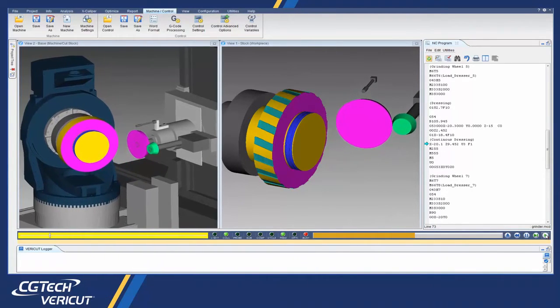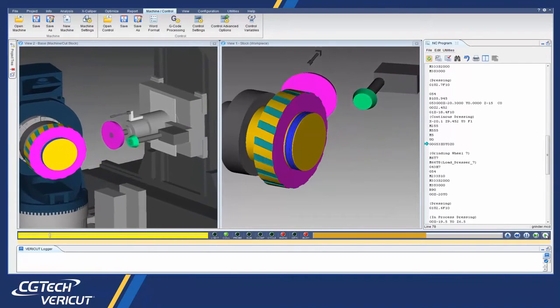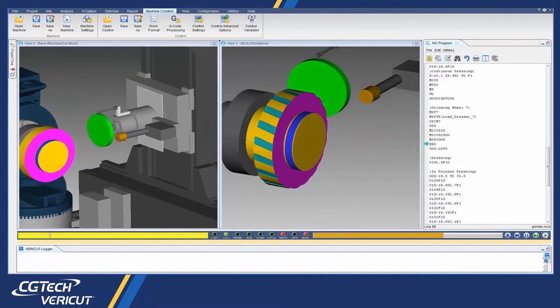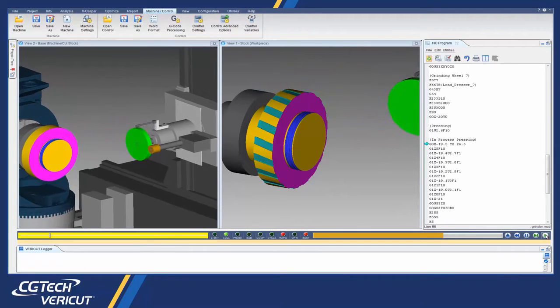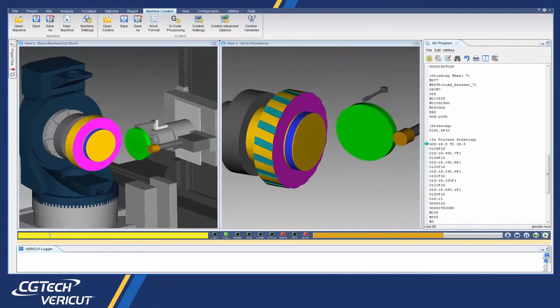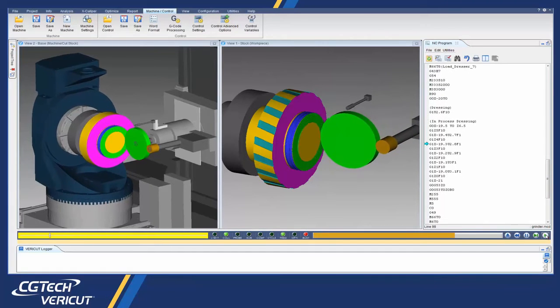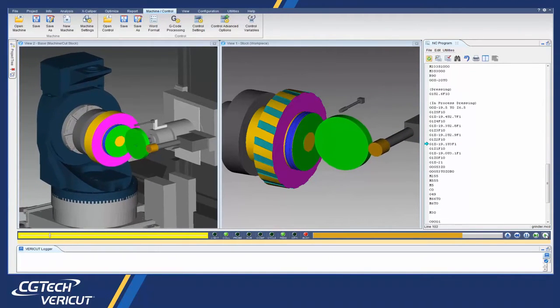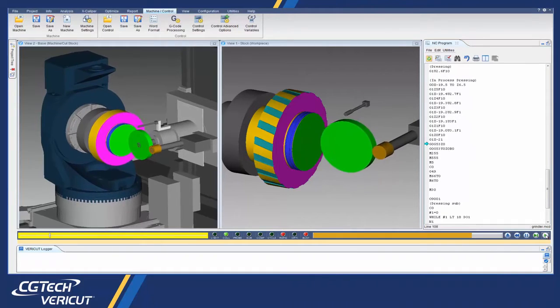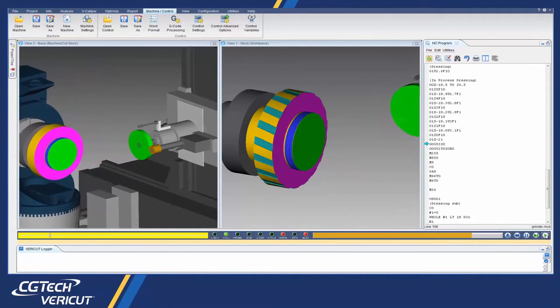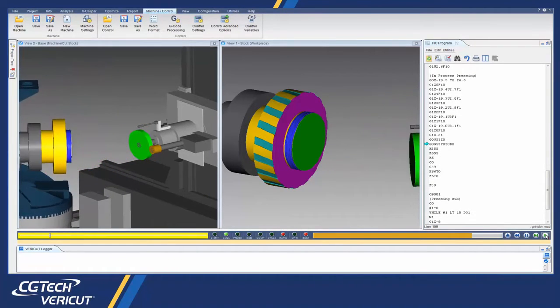With these enhancements, Vericut now simulates continuous dressing while the grinder is engaged with the part. These types of operations are supported regardless of whether the dresser is spinning or not spinning. And that's it. For more information on Vericut's new grinding and dressing capabilities, see the Vericut help.